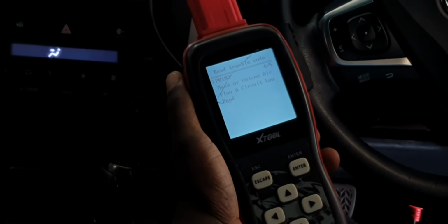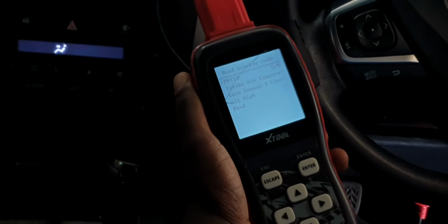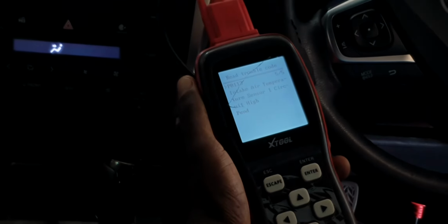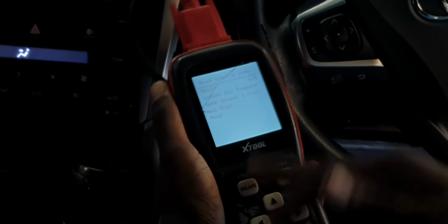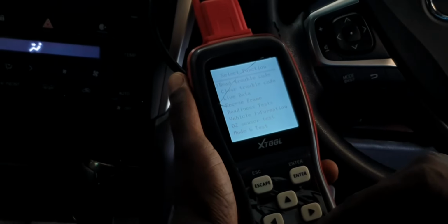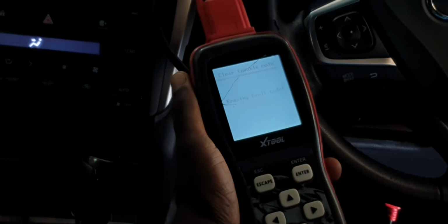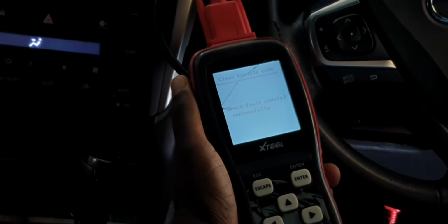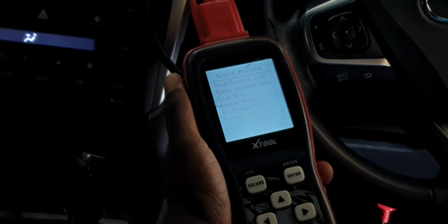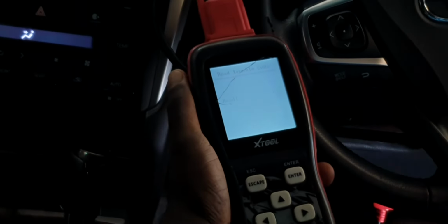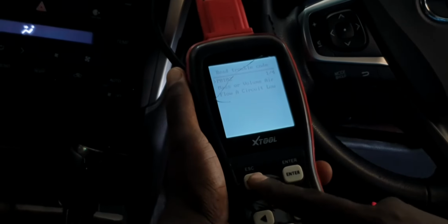We have mass airflow sensor again. We have intake air temperature sensor again. So we have it 5 times. So the first order of business, we can store it, with a more advanced scan tool we can store it, or write it down. Now we can just escape and erase this code, clear diagnostic trouble code and see what happened. Erase code successfully. Alright, let us read the code again. Still have 4 codes. Still have the mass airflow.